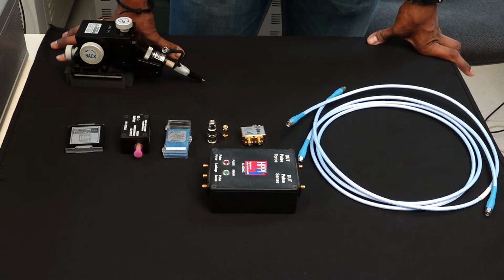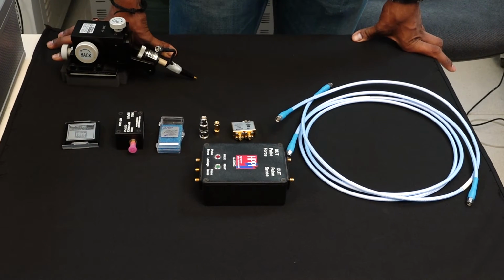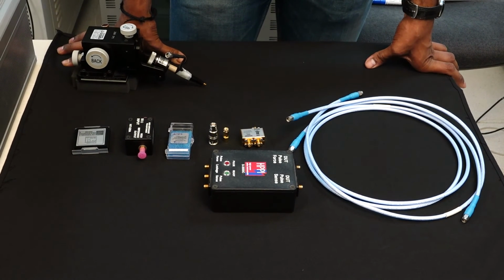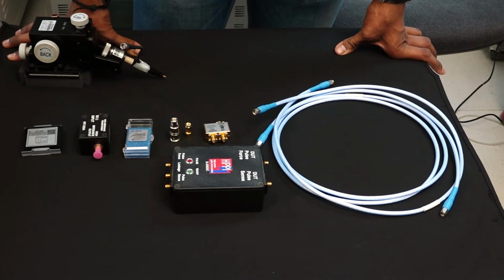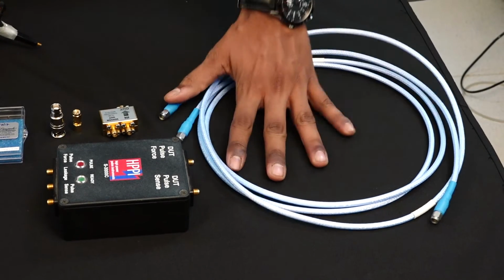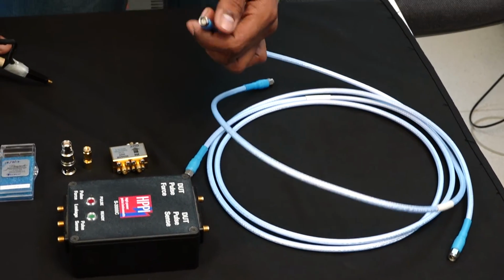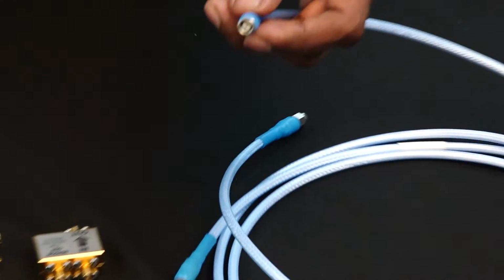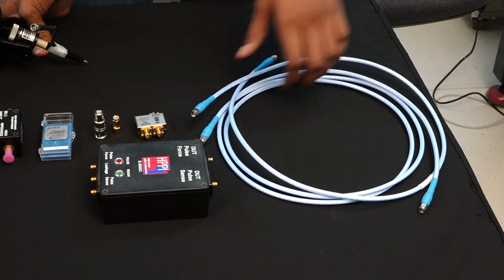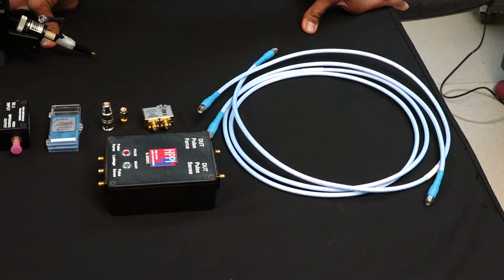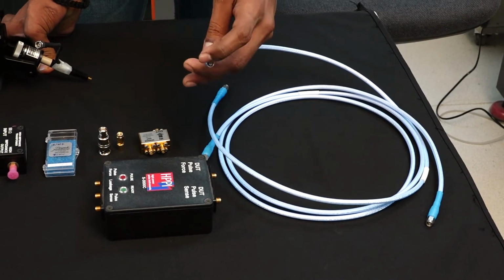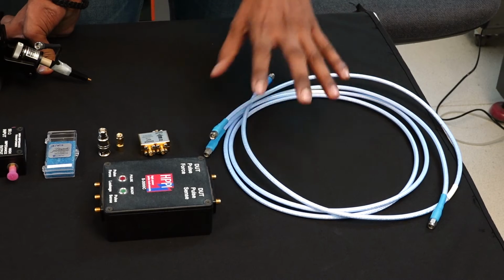So when I was talking about the whole TLP circuit and discussing the schematic of the whole setup, I was talking about different components that are very important. The first one that I was talking about is a transmission line. As I told you, a transmission line has a characteristic impedance of 50 ohm and that's important because it reduces the mismatch at different points in the whole setup. So now this here is a transmission line that we use. This transmission line has an inside signal pin here and the outside shielding that serves as the ground. So these are all SMA cables. The good thing about these cables is that they have a very high dielectric breakdown. So basically, if you apply a very high signal voltage to the inside pin, the whole cable would not get damaged very easily. And secondly, it has a 50 ohm characteristic impedance.